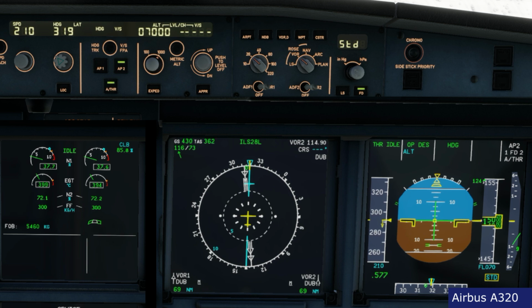You see the rate is descending, we got 900 feet per minute, and if this is not going to be enough, the aircraft is going to reduce even further the rate to 500 feet per minute. At the moment it looks like it's going well, so the aircraft operates smooth changes. This is actually the Airbus, as a matter of fact, thanks to the flight augmentation computer, which is capable of more complex calculation, making smoother corrections. So you see that at the moment 900 feet per minute is a reasonable compromise between loss of speed and loss of altitude, and that's what we're maintaining. Other autopilots will eventually even climb in the attempt of reaching 210 knots faster.